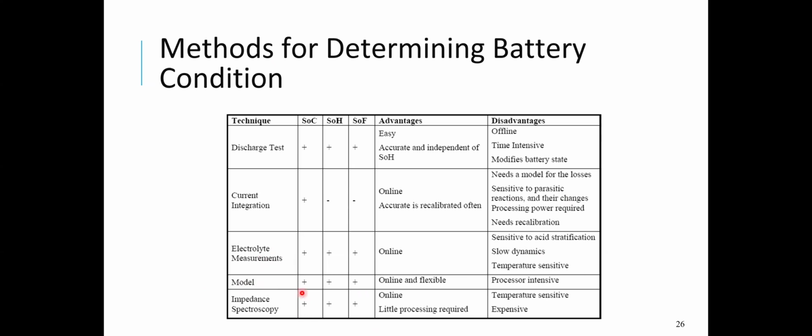And then I can do these crazy tests where I inject currents of different currents and voltages of different frequencies into the battery and figure out how it works. And there are many, many other ways to determine the battery condition. Many of them use some kind of intelligence, like machine learning and filtering to basically take quantities I can easily measure, voltage and current, and figure out what is happening with the battery. And that's a very interesting problem that's still being researched.